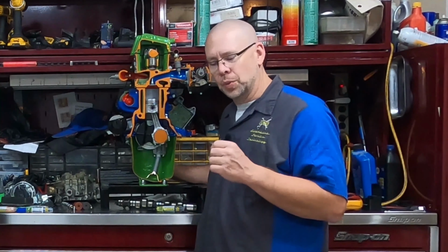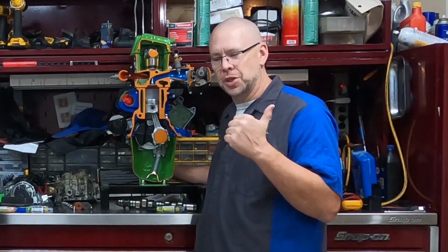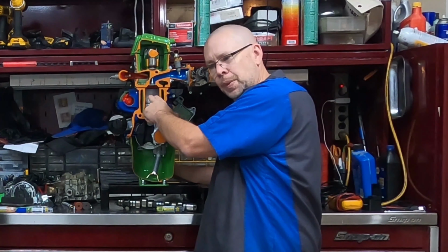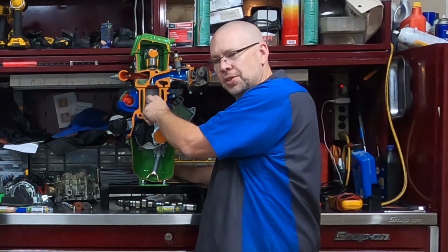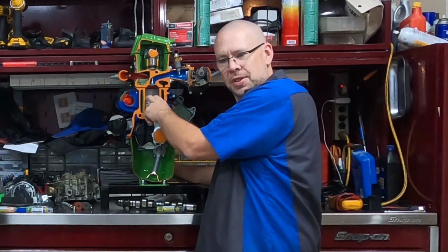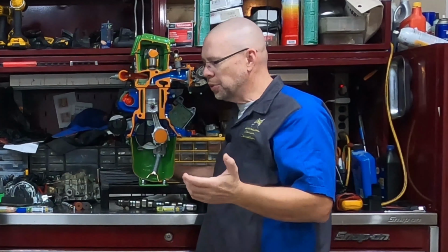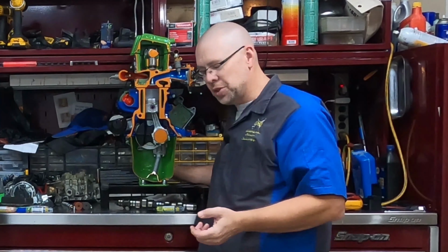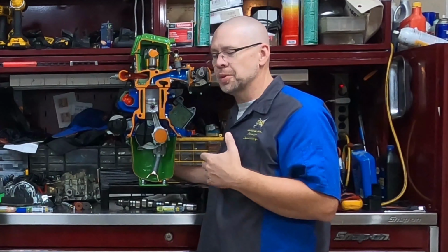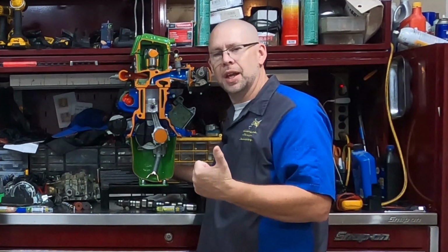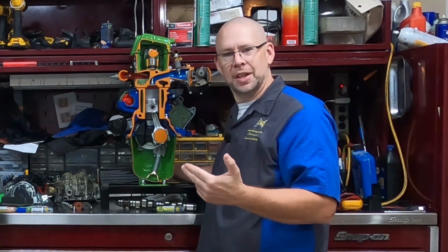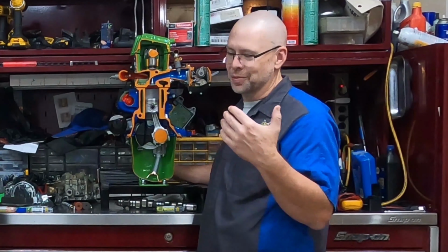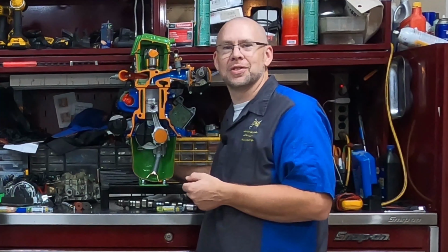So timing, we need to have it, because as we change speed, as we change load, as other factors change, it changes the amount of time and other factors inside that cylinder, so we need to change when that spark plug ignites. If this was just a stationary engine, we wouldn't have to do that. So we have to change it. Now it's just up to the PCM. The why we change it: speed of the engine, load on the engine, design of the engine, additions to the engine, i.e. forced induction, nitrous, those other kinds of things.